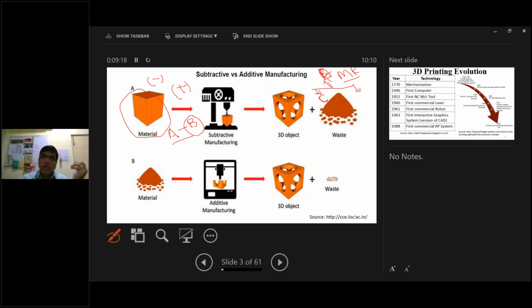We go like laser, electrodischarge, plasma, electron beam, ultrasonics. They are erosive, or water jet or AWJ. So that is nothing but your A minus B. A minus B itself is a very big world, and you have lots of technologies within this, and many of them are advancing very fast. But the world is A minus B. Okay, well, that is subtractive manufacturing.